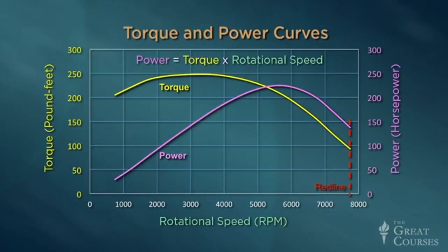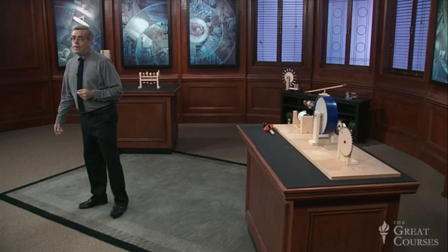First, as we've seen, an internal combustion engine is incapable of running at significantly below its idle speed, typically around 800 RPM. Thus, when the vehicle is standing still, the engine must be disengaged from the drivetrain or it'll stall. Second, because of the tremendous forces that are being transmitted through the gearbox whenever it's in gear, the transmission must be physically disconnected from the engine to change gears.